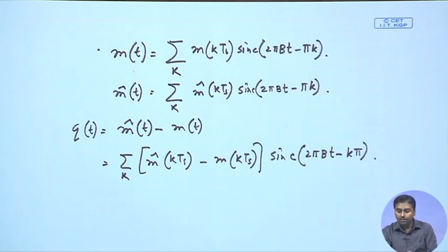Whenever you go from analog communication to digital communication, this is a particular noise which is created at the source. So far, all the noise that we have talked about was either generated at the transmitter circuit, which was very negligible, so we never considered that, in the channel, of course, and in the receiver circuitry. So, mostly in the channel and receiver circuitry is where the noise was. Now, this is the noise which is being created at the encoder. So, whenever you are quantizing, you are potentially creating noise. So, this is source induced noise. Your process of transmission is generally creating this noise.